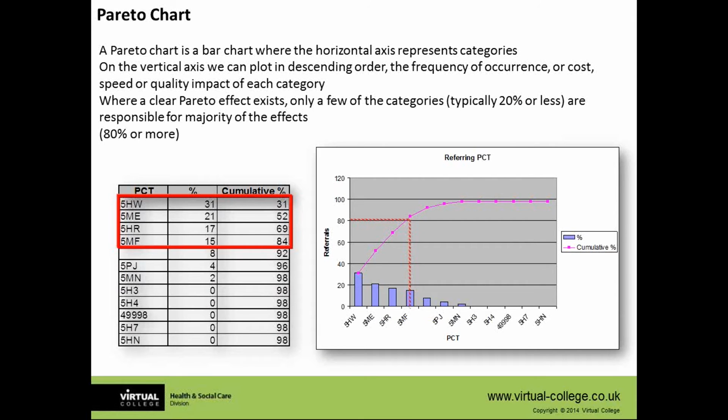Okay, so here's a big warning. I like our big warnings in Lean, but basically you need to understand how you gather data and be fully familiar with the system and processes being examined and how the data is being collected. So with the 7 quality tools, how people gather data is important. Everybody must gather the data the same way. Do they go to the same decimal point? Are they rounding up, as noticed by the hedgehog example? Are they measuring height with shoes on or off? Are they including breaks, etc.?